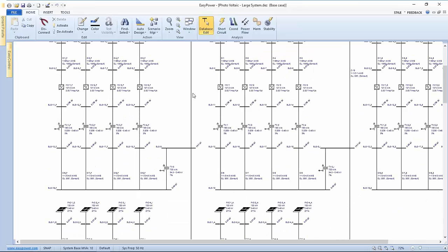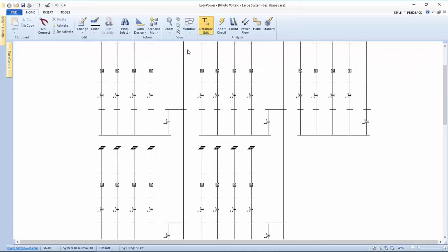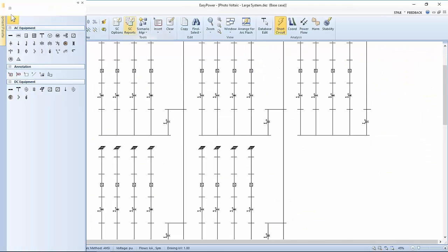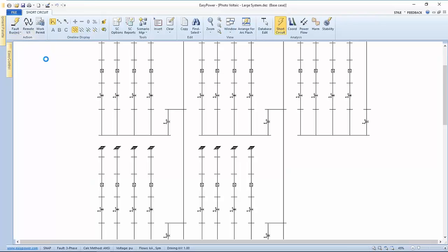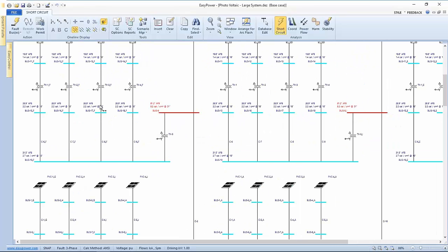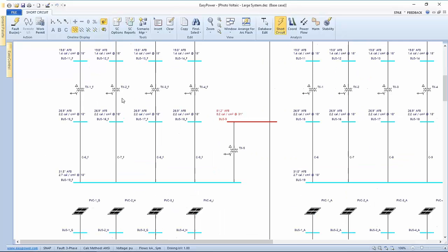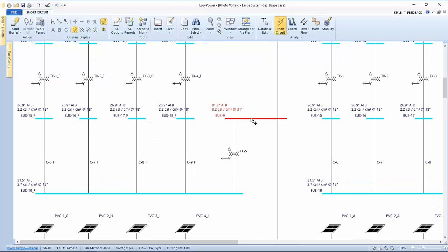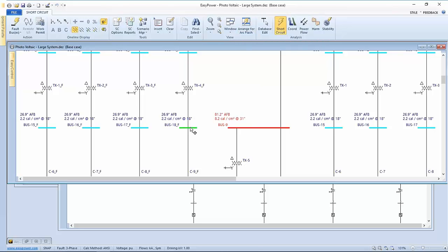And so this actually also makes another point. If we go into the short circuit focus, fault the buses, and look at incident energy, we can see that on the individual buses or individual feeders, we have relatively low energy, but when you sum them and take the voltage up, we're talking about more substantial incident energy calculations, and it's worthwhile noting.